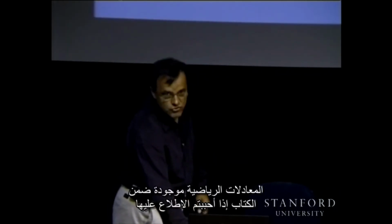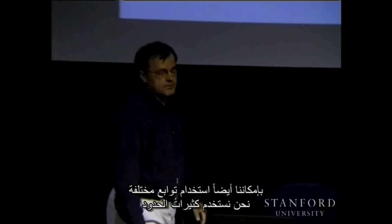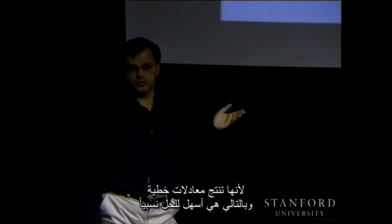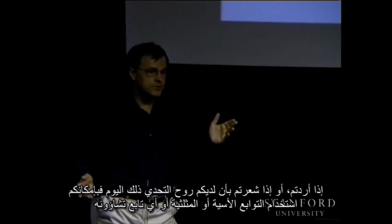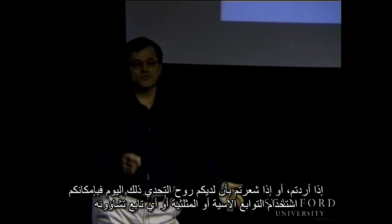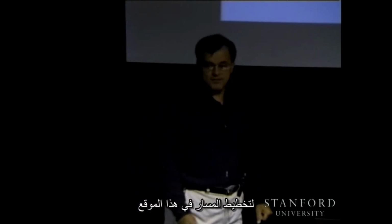The formulas are actually in the book if you're really curious to see what they look like. Now, another thing is we can use different functions. We're using polynomials because they result in linear equations, so it's relatively simple to solve. If you feel particularly challenged that particular day, you can use exponential functions, trigonometric functions, whatever you want, to plan the trajectory in the space.